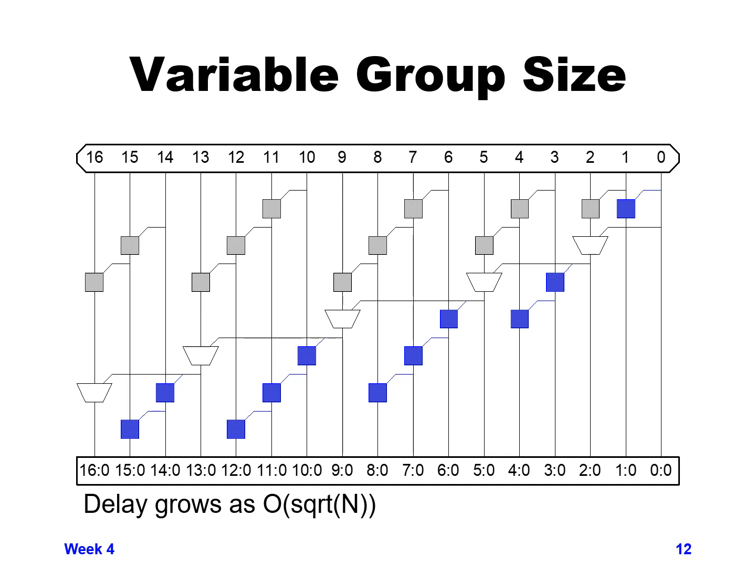So now we're at 7 stages, whereas the design in the previous slide was 9 stages, and the full carry ripple adder was 16. So at 7 stages, we're now less than half the number of and/or stages than we had in the carry ripple of 16. And so this is actually a faster design than just breaking up your bits by equal number of bits per grouping.